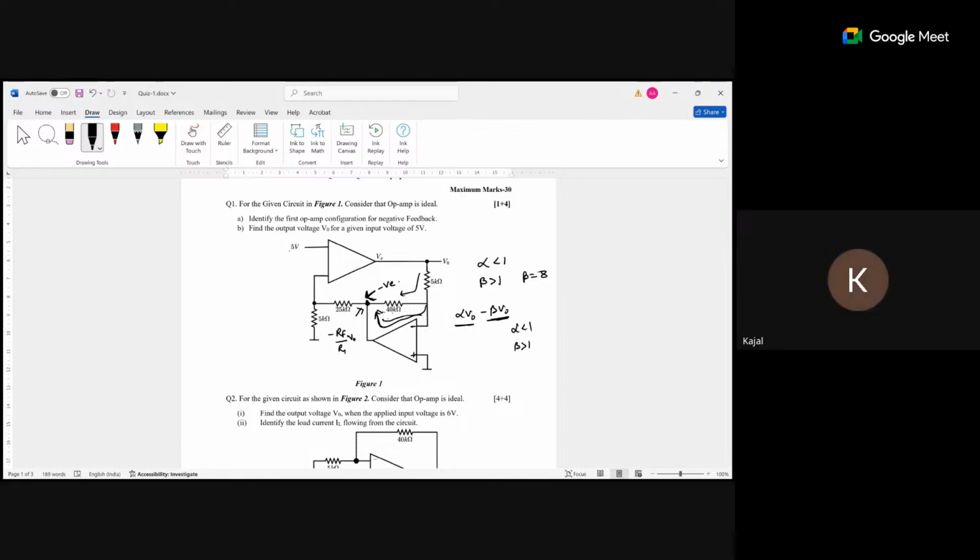Now this negative voltage will come here at this point. If I multiply with the negative voltage, negative voltage also there, it becomes a positive voltage. So we are getting a positive. If we apply the positive voltage and we get the positive voltage, that means there is no negative feedback. This particular feedback is a positive feedback.